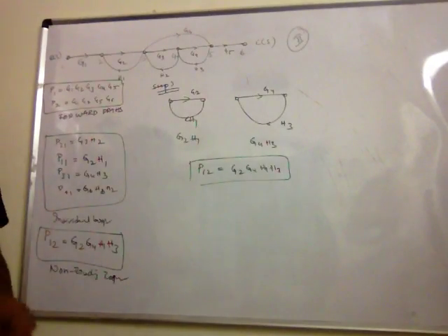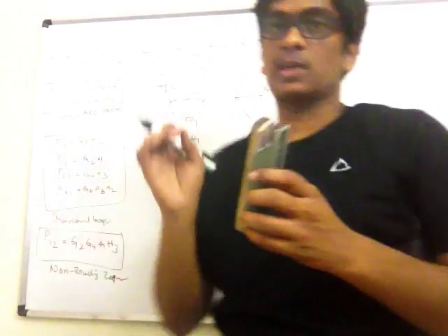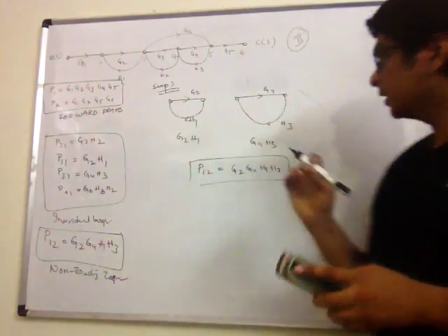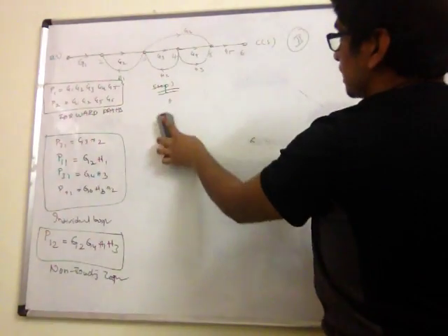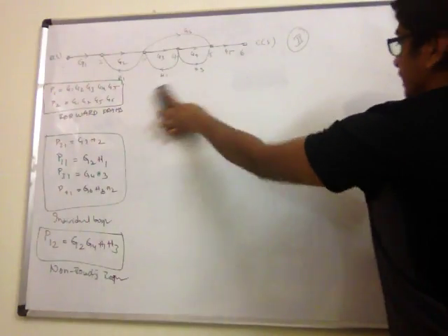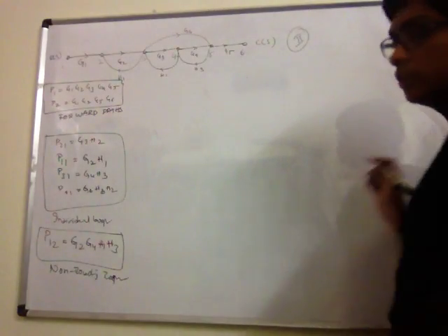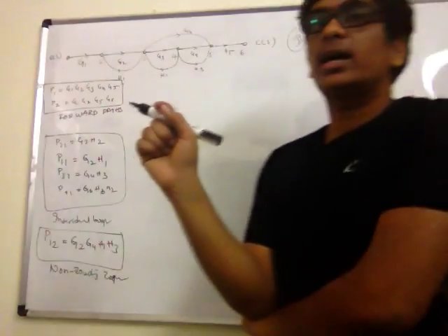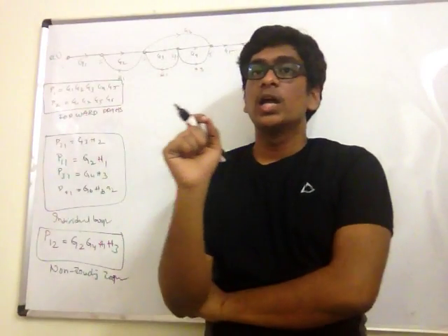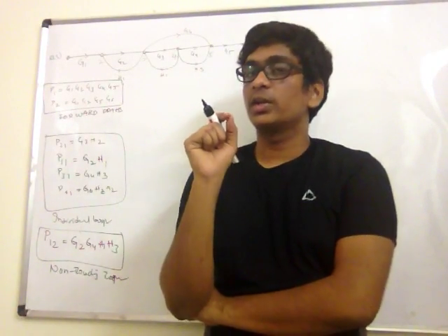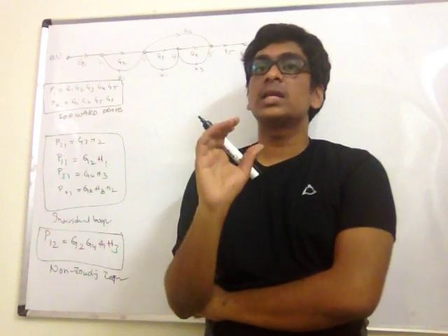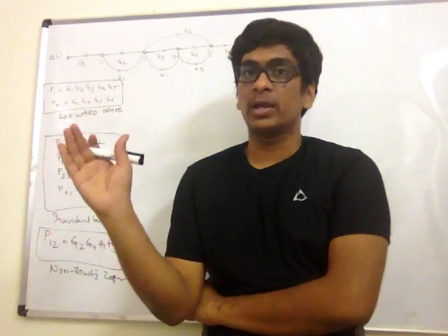Non-touching loops. Now we are really closing in on the sum. We are in the final or the pre-final step, step 4, which is the calculation of delta and delta K. So before we actually start look into the fourth step, let us see what the Mason's gain formula is.